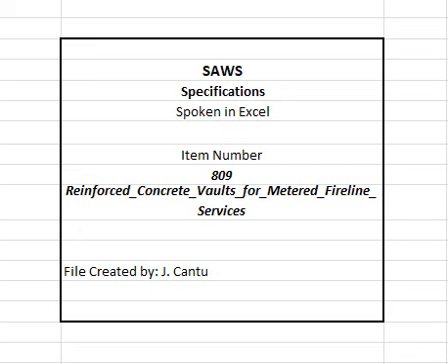809.5 Construction. 1. Concrete work shall be as per specification item number 808 reinforced concrete vaults. 2. Painting. All exposed metallic surfaces such as the cover plates, hinges, handles, and other exposed hardware shall be primed and painted with 1 coat of primer and 1 coat of aluminum paint of approved and compatible quality.